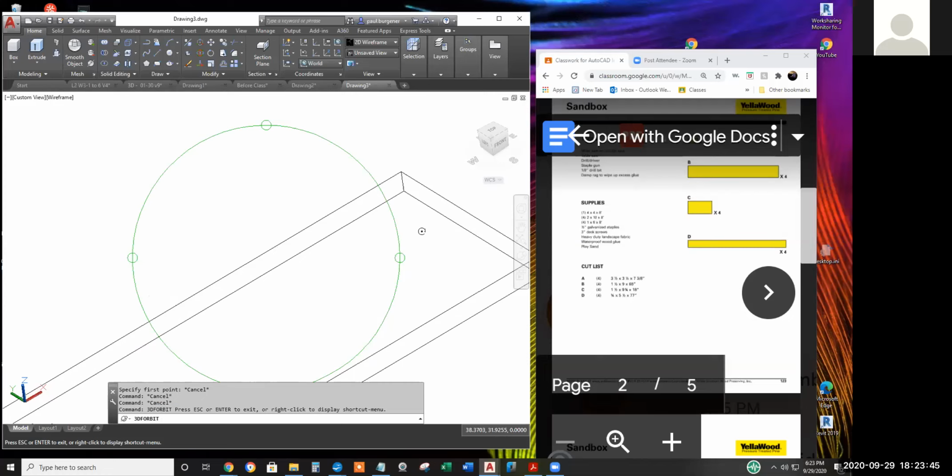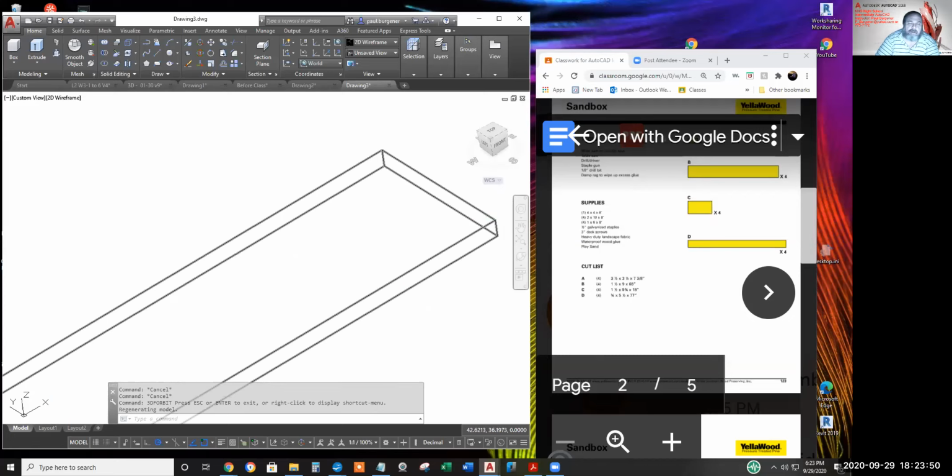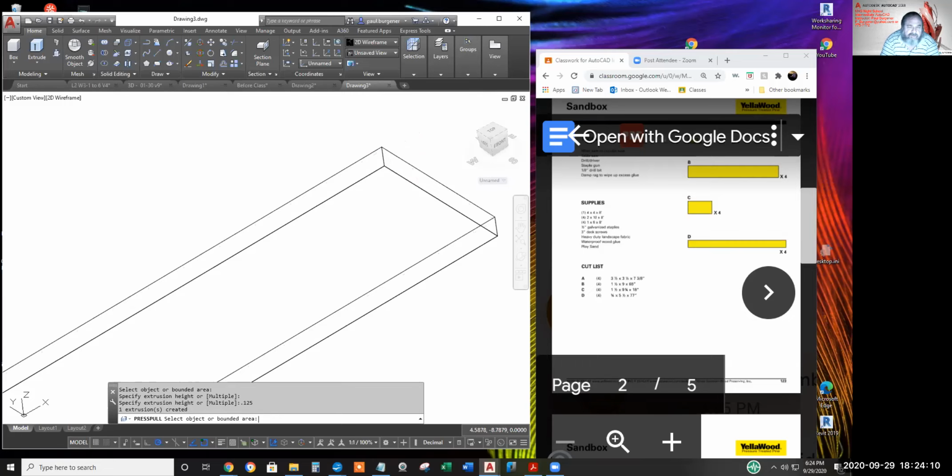Excuse me, Paul, you made that 0.625 instead of 0.750. Always something. All right, let's use this press pull. I think I can latch onto the top surface and drag it up by 1/8, 0.125. DI enter again. Click, click. Thank you. Back to 0.75.